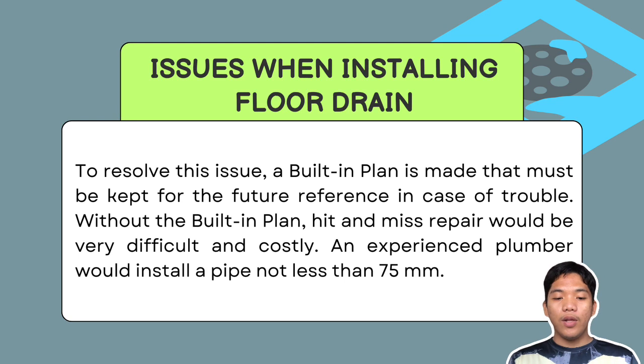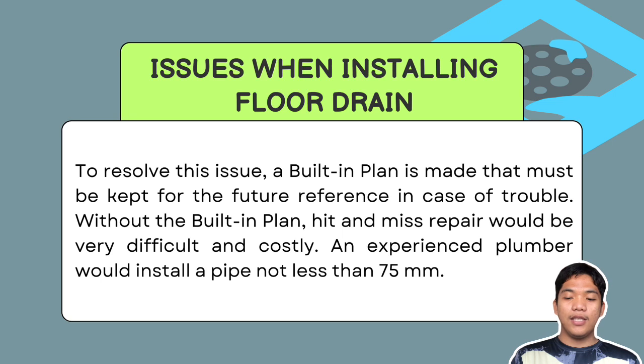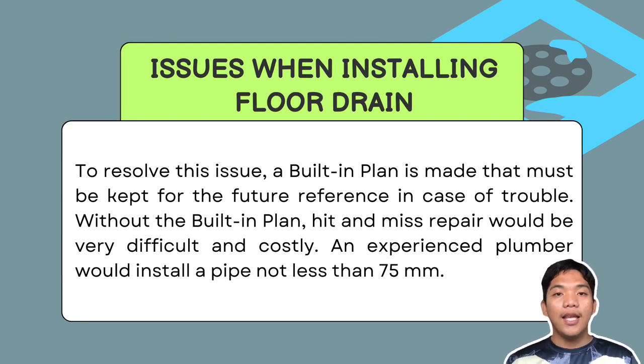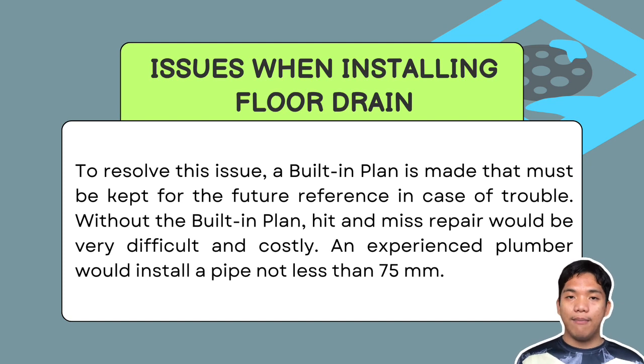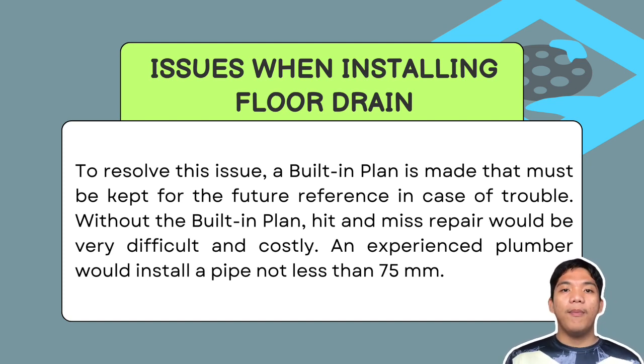More so, when it will be installed underground or embedded in a concrete slab, the difference in cost between a 50 and 75 mm waste pipe for a short distance floor drain and P-trap is immaterial compared to the risk and inconvenience that will be encountered in case of drain trouble. So, just what I said, kailangan, when it comes to installing a floor drain, ang kailangan one thing and main ifo-focus talaga natin is iiwasan talaga magkakaroon ng pagbabara.